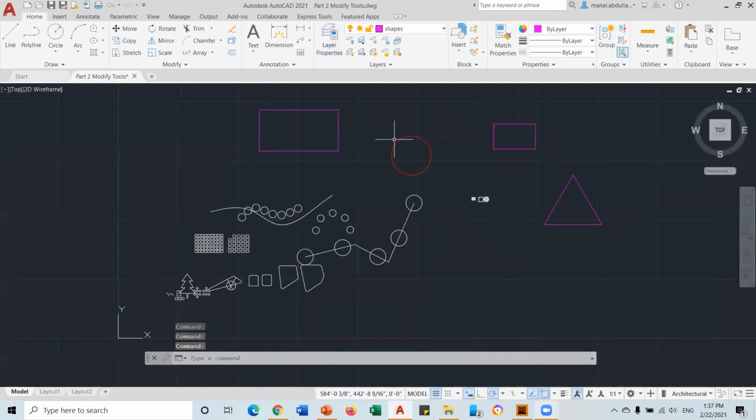everything in that layer. It's very important to create layers and organize your project. For example, if you are drawing a house plan, all walls should be on a layer, and windows on a separate layer. You need to create unique layers for windows, doors, walls, furniture, dimensions, text, and the more organized you are, the more professional your project will be.